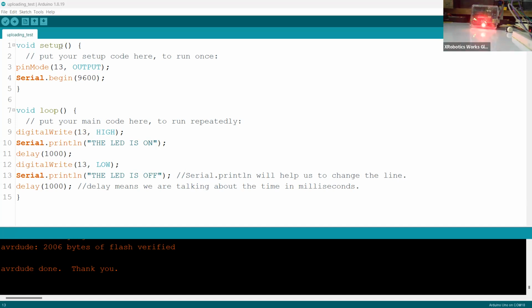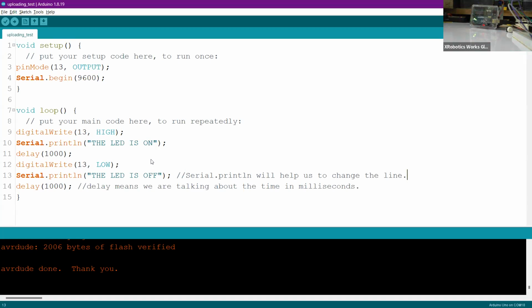What is actually happening with the microcontroller, and you will ask each and every person for help. So make sure to utilize the Serial.print function for the debugging part, where you can see whether your program is actually executing or not, or if you have some problem with the electronic components, the sensors or the output devices. Okay, so I hope the concept is clear for the Serial.print function. Okay, so let's go.